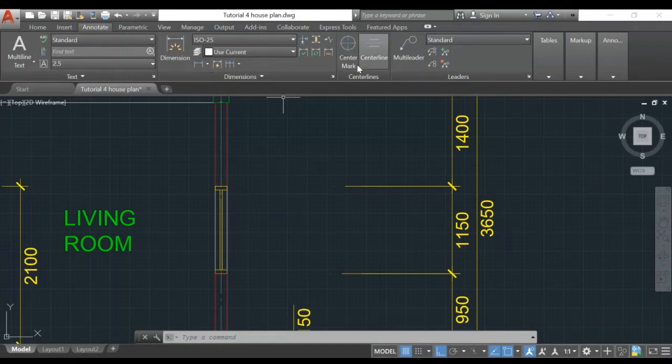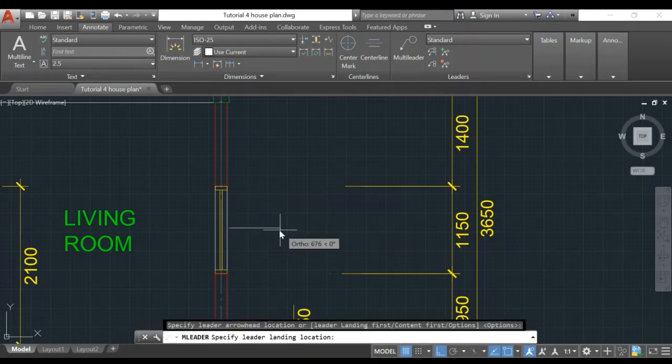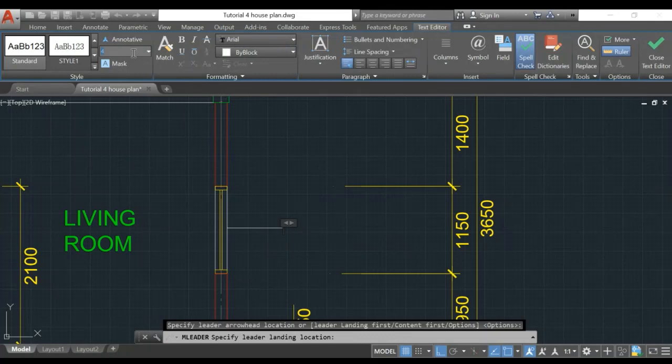Let's do the specification example here. I'll do the special window here. Right click. Okay, I'm going to change the text size to about 90, because this should be printed out at a 150 scale, right? So 90, 90, 90, enter.